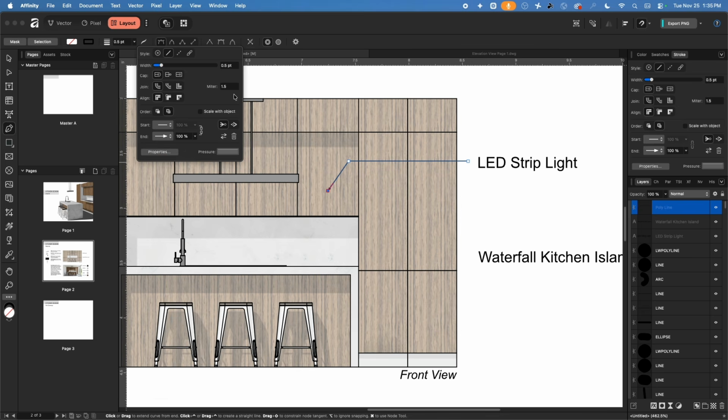And the line should not be too big. It should also be a dashed line. So maybe go to dash and then say 10, 10. This is too big. What about 4, 4? This is better. The line is a little bit too big, 0.25. Now the arrowhead is really tiny, 400%. That makes the arrowhead bigger because this is in relationship to the stroke.